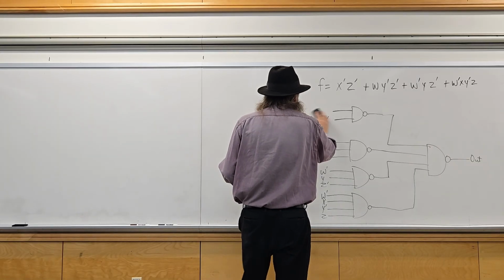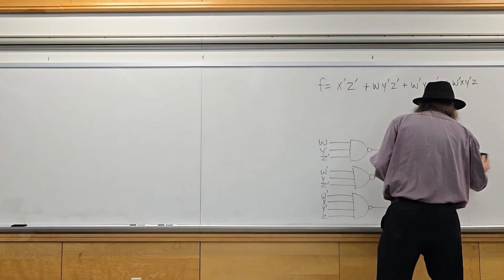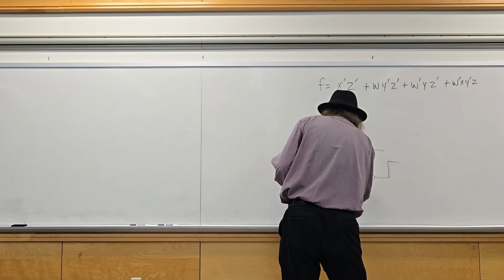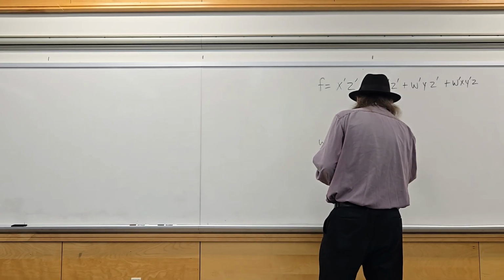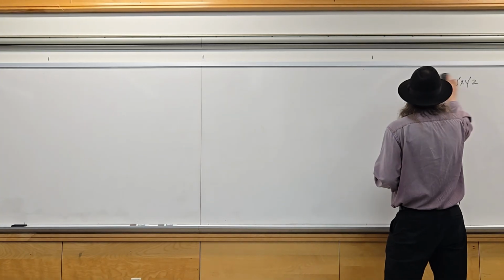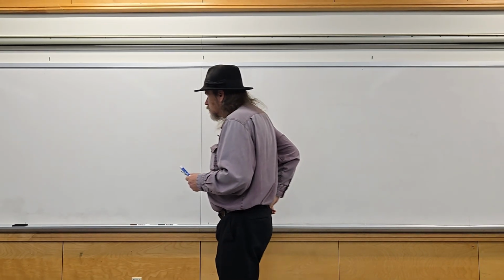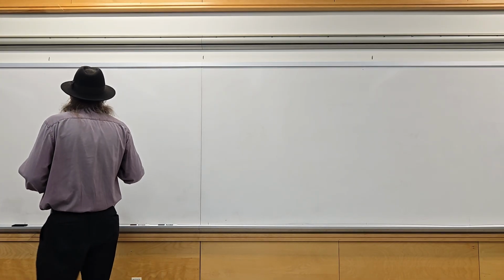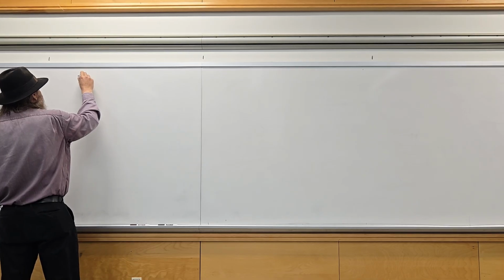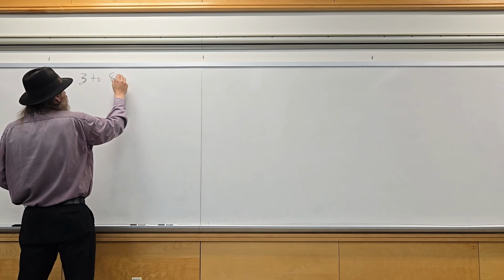One of the more common ones is called a decoder, where it takes as an input a binary number and then asserts high on one of the multiple outputs. We'll do a 1 to 8, no, I'm sorry, 3 to 8 decoder.